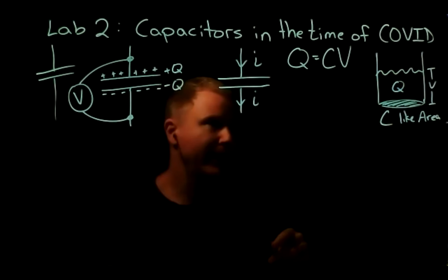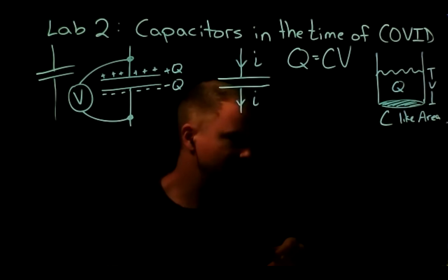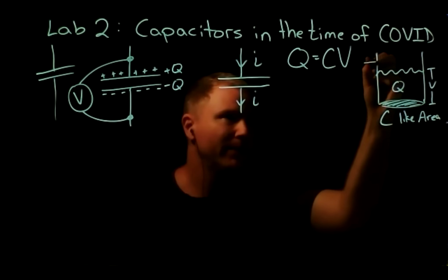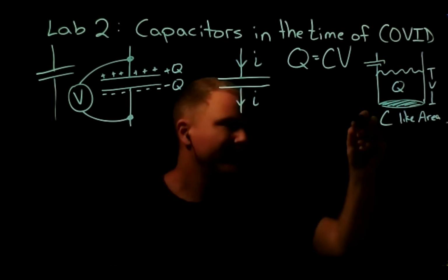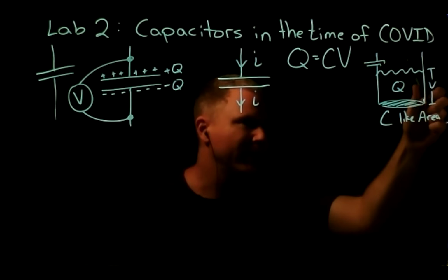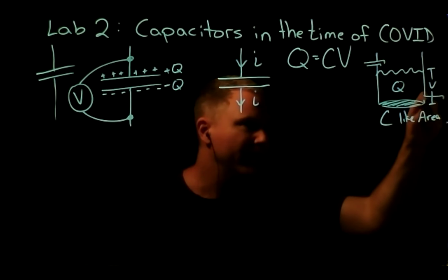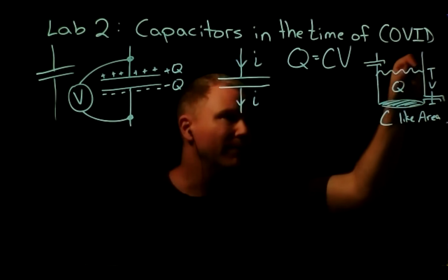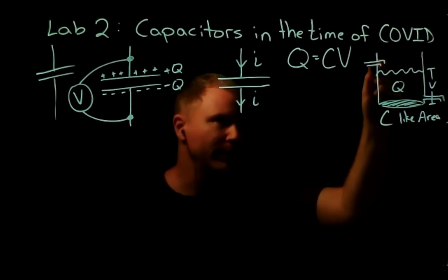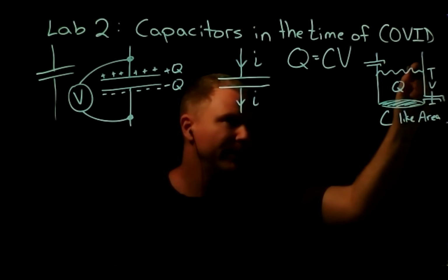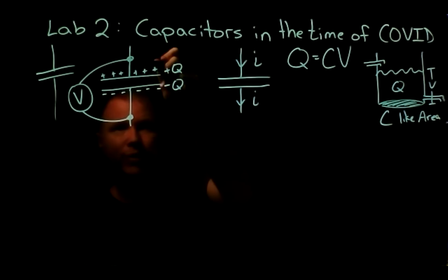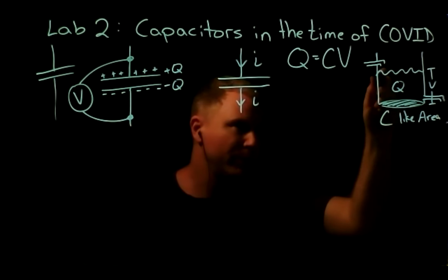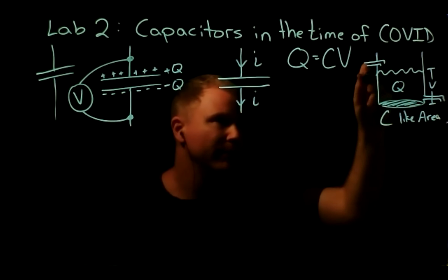But the best way to think about it is just this tank that holds water, and the wider the tank, the bigger the capacitance. And you can imagine putting water in with a little spout that's coming into the top here, and taking water out the bottom. Here's a little spout that comes out the bottom. And the water that comes out the bottom is at a lower height, if you want. If you actually charge a capacitor, you're basically always putting water right at the top water level and taking water out right at the top water level, right? Because the voltage of this conductor here is always at the top. So you're always just putting water in right there and taking water out right there.